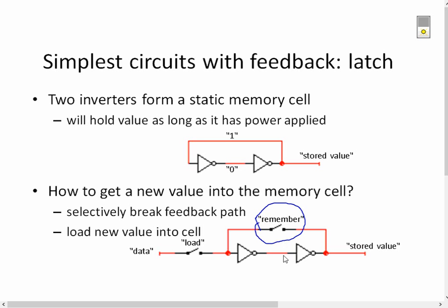When I close it, it creates that feedback loop, that mechanism that says feed the input back in, so I give this continuous cycle going on and on. But of course, I can open the switch at some point in time. When I do, it allows me to set another value or to lose the value, to reset it. So this is what we mean by the ability to selectively break out of the feedback path.